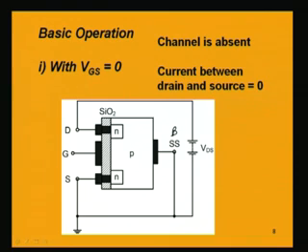So, that will have a high resistance, so there will not be any flow of current, and this PN junction is also reverse biased. So, these two back to back PN diodes have reverse biased junctions. From this end to this end through the P, if we travel, we have NP and again PN, and both these diodes are reverse biased. So, we will not have any flow of charge carriers, or we will have zero current. There will not be any flow of current from the drain to the source.